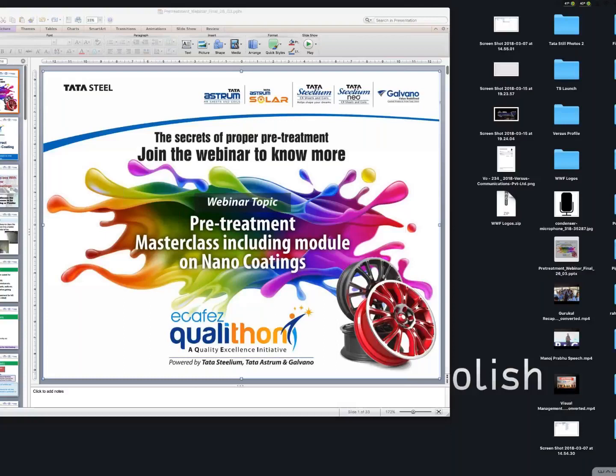And HCl will clean definitely, but it will not give you a very good phosphate also, because it is going to make the surface more and more reactive. So the phosphate layer also will not be very good.